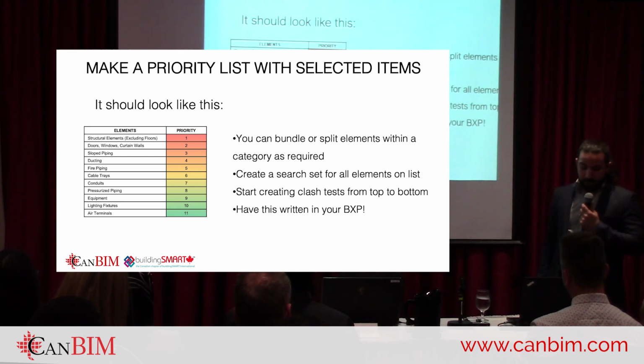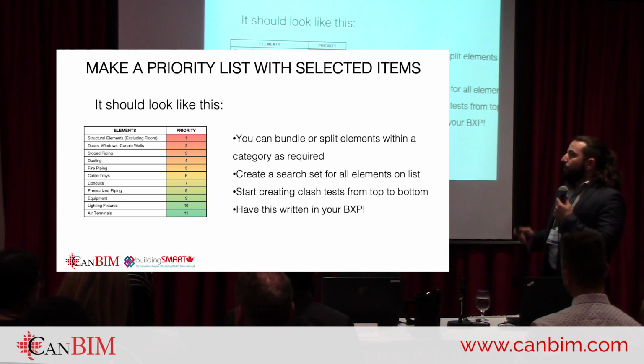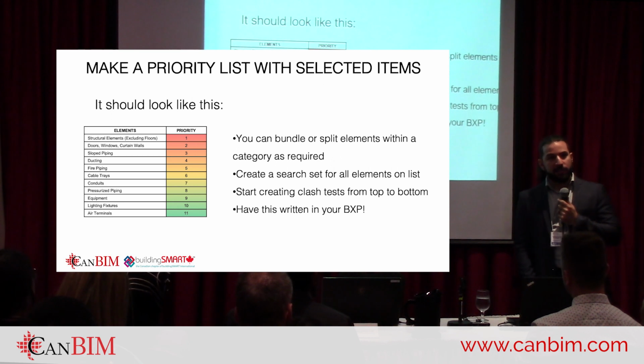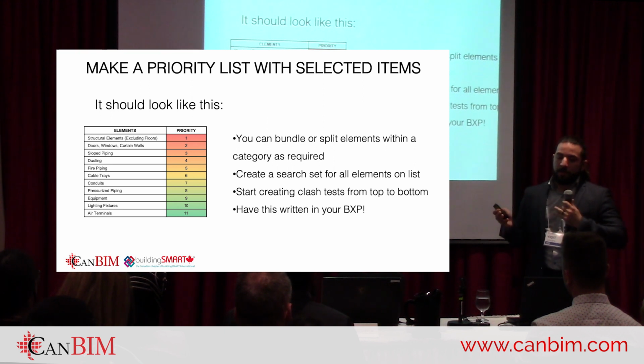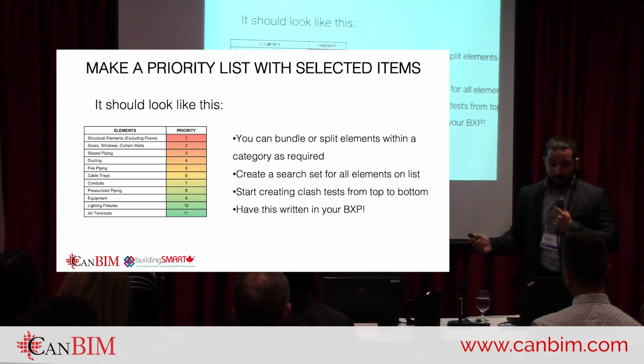Okay, and this priority list will also determine in which order we're resolving them. I found in the past that if you issue all your reports at the same time, when people are moving things to avoid items, they're just creating other clashes because 5 people are changing the design at the same time. So doing it in order is usually a good idea.